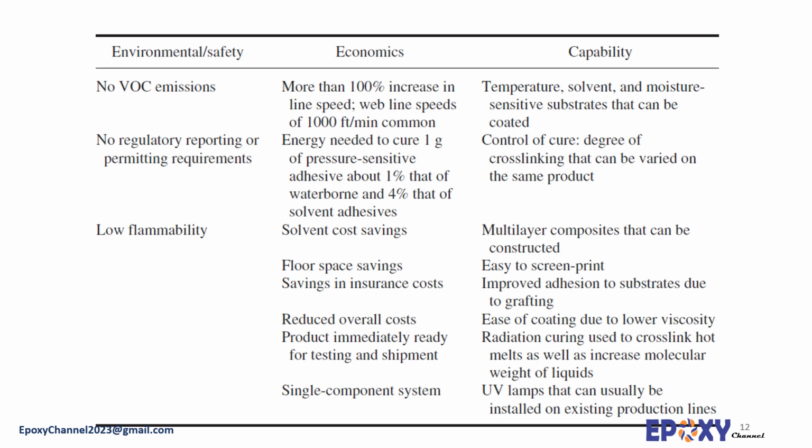In radiation curing, there are some main considerations, including type and source of radiation, nature of the photoinitiator and the resins to be cured, and final properties required in the cured product. The effect of radiation dose on the UV curing adhesive system is that as the dose increases, the molecular weight, MW, increases. This consequently results in a decrease in peel strength and an increase in cohesive strength. Chemical resistance and thermal stability of UV cured systems are also generally increased by a greater radiation dose.